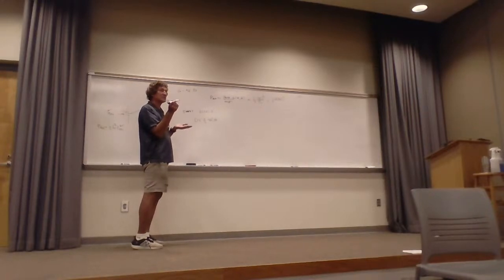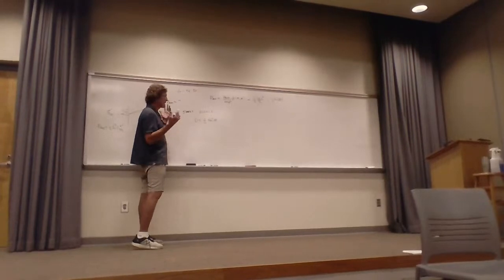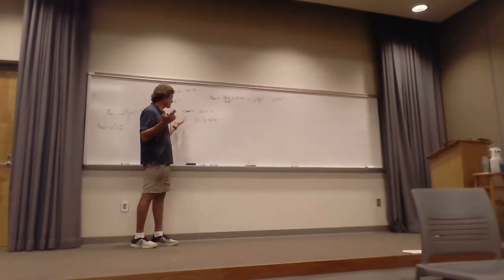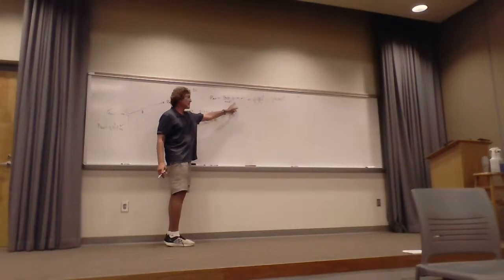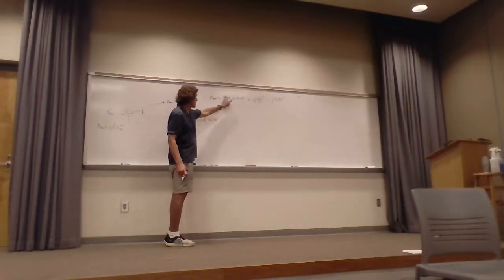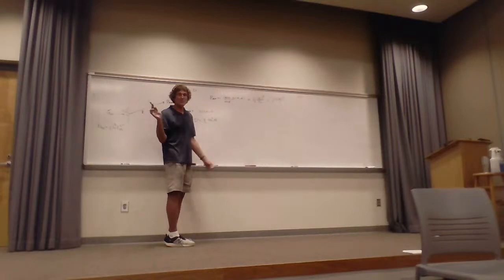And that relates to beam width? Well, the directivity and the gain are together, right? One is proportional to the other. Assume the efficiency is 100% or the value is 1, so directivity is gain. If you take this and put it in here, then you see these terms are a scalar value at a given distance r away, right? So if you were to plot this, you see that when the directivity has a maximum and goes down to 50% or 0.5 of its maximum, you can easily figure the beam width, regardless of the mathematical functions. You all with me on this?